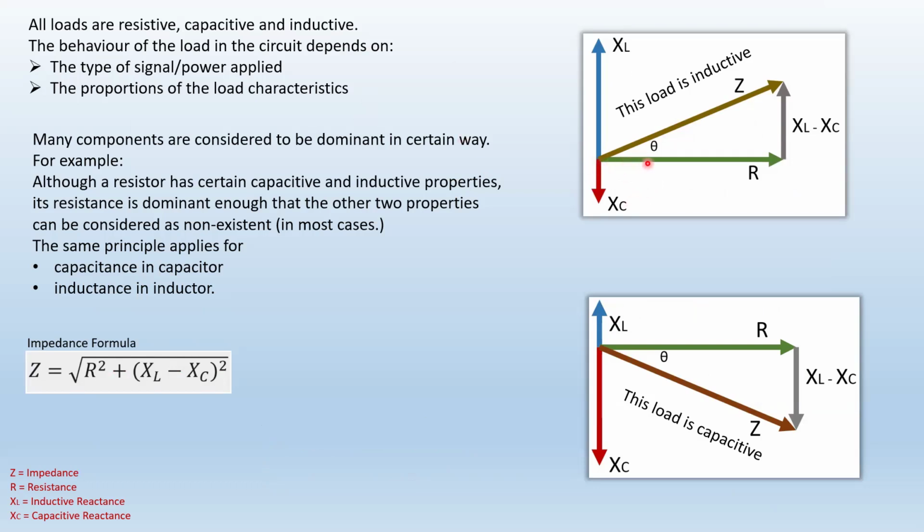Here is the zero reference, pure resistance. Why do we have pure resistance? Because there's that resistor in the circuit that we drew in series with all this stuff. So we're analyzing the whole circuit now. So here's the resistance value, and the resistance value is going to be at the angle of 0 here because it remains constant. So the voltage and current at the resistor are in phase. The resistance has a 0 reference angle.